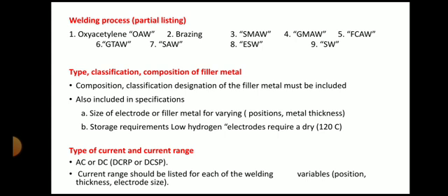Then the storage requirement. For example, a low hydrogen electrode requires dry storage at 120 degrees Celsius. So how you are going to store your electrode before welding, that information you have to provide in your WPS.